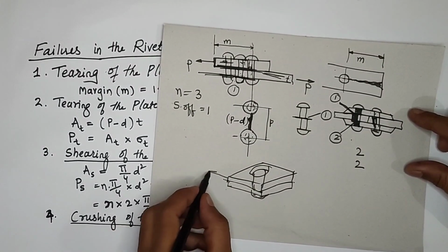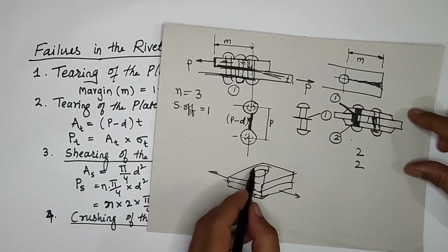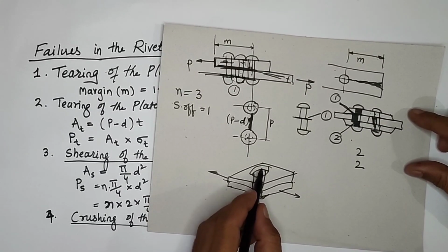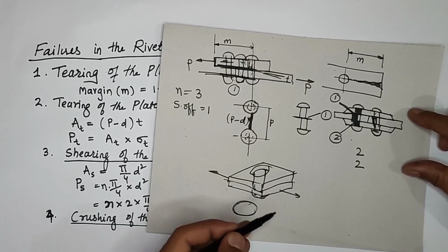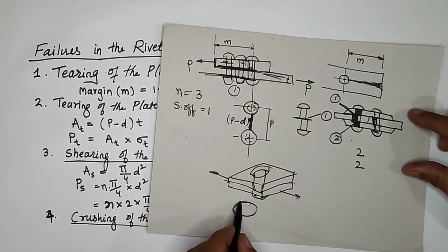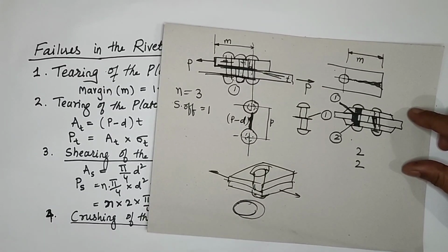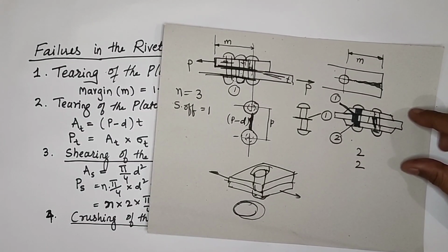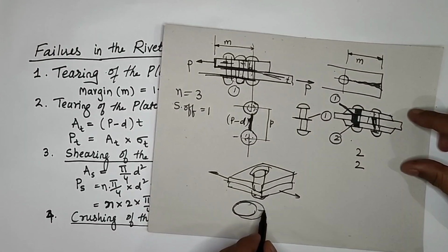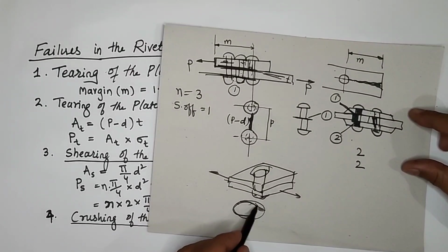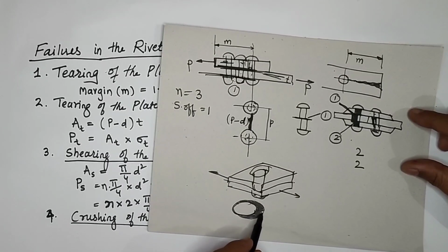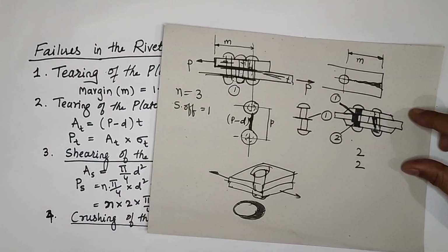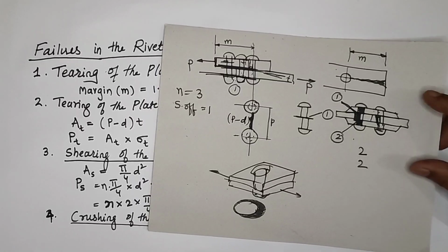So now if you apply some forces here, due to that force, the rivet changes the regular circular hole into a different shape. Sometimes it may be oval shape, sometimes it may be irregular shape. So that makes the joint loose. Okay, so there may be a chance of some leakage of fluids. So different cases may happen. To avoid that, we have to provide more strength in crushing.